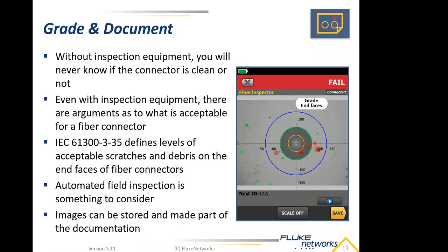And that is usually, or sometimes, down to the work practices of the client. They do not always clean the end faces before they plug stuff in, and the net result is that you end up with end faces which are either dirty or damaged or both. But if you have end face images from when you left site, so at the end of testing, then you have decent defense that it is not your fault that the fiber isn't working.